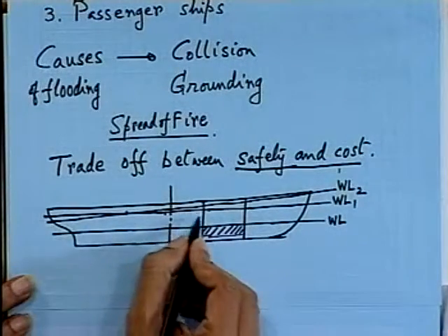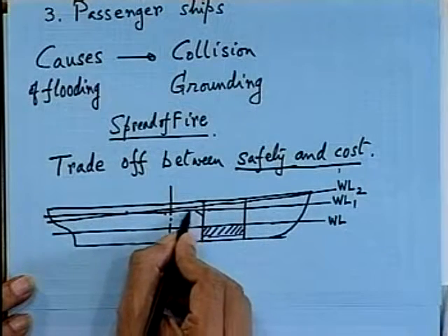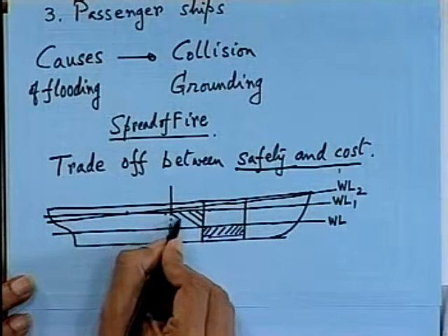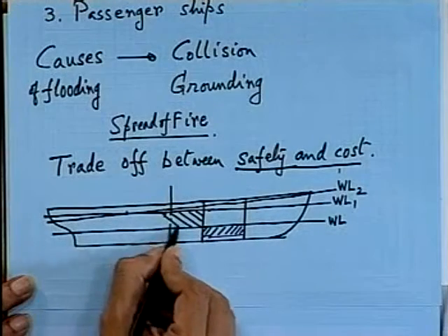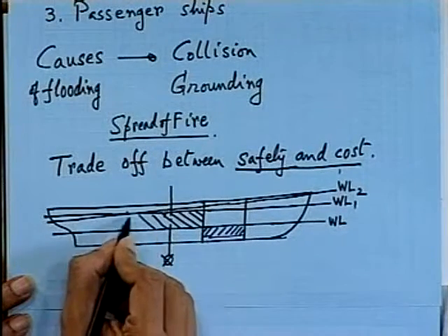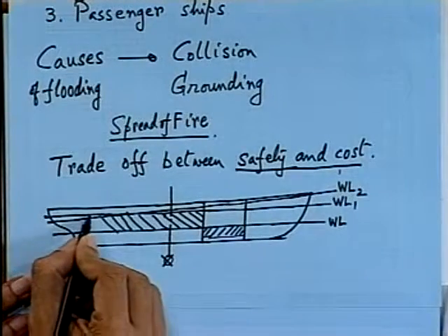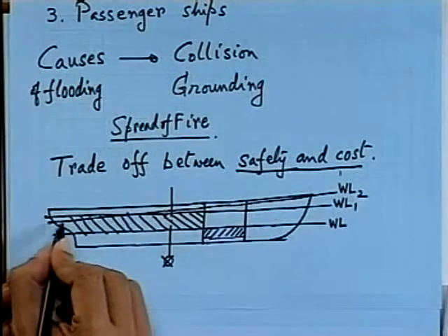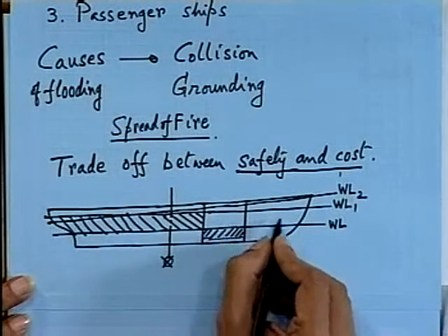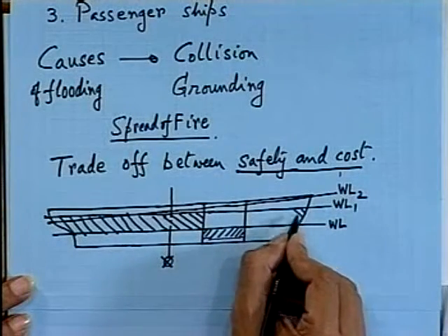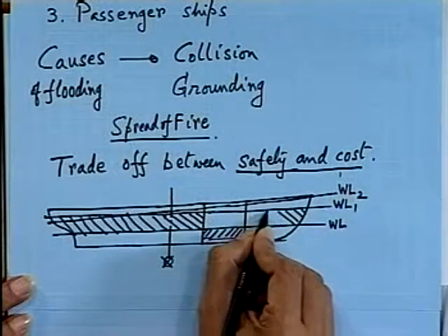I told you the buoyancy that has been lost is to be made equal to the buoyancy that has been gained by the ship sinking to a draft WL1. So this shaded portion is equal to your lost buoyancy.